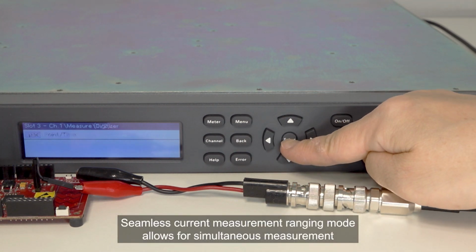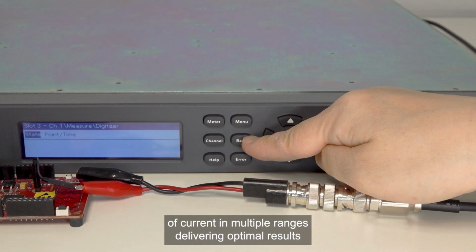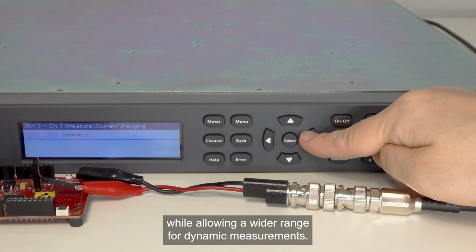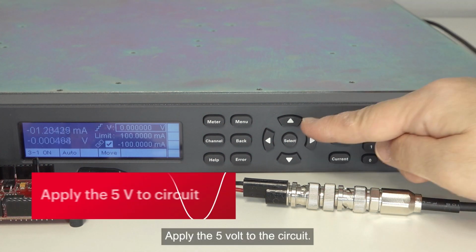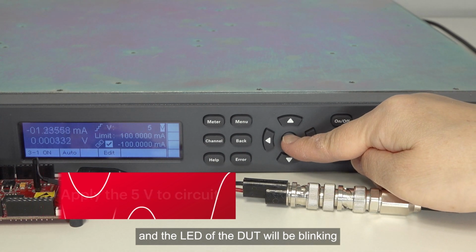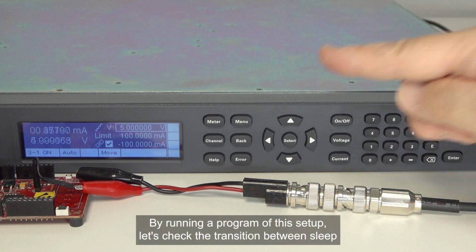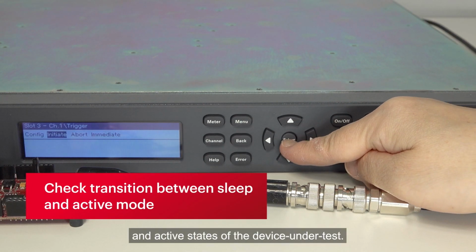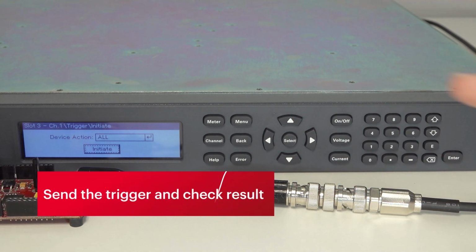Seamless current measurement ranging mode allows for simultaneous measurement of current in multiple ranges, delivering optimal results while allowing a wider range for dynamic measurements. Apply the 5 volt to the circuit and the LED of the DUT will be blinking when it is active every 1 second. By running a program of this setup, let's check the transition between sleep and active states of the device under test. Just send the trigger.